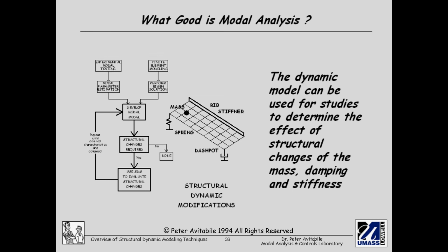Right? So we have these modal characteristics, and it doesn't matter whether it comes from a finite element model or from a testing model. I can study the effects of changes of system characteristics and how that affects the performance of the system without having to build the actual changes. So we're going to study this to understand what's the best way to modify the system before we build it.